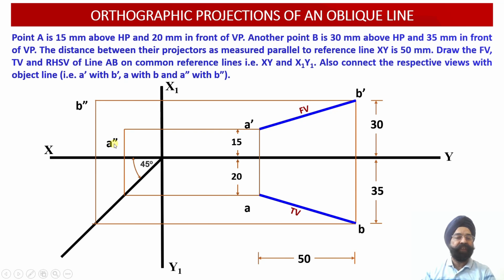dash. So once again we can check, here we have got the top view construction corresponding to the point A. So this distance we have transferred onto the transfer line and projected this point A into the profile view projection, and extended this vertical projector line up to the horizontal construction line which is emerging from the point A dash. Wherever these two construction lines intersect, we are going to obtain the location of the point A double dash.